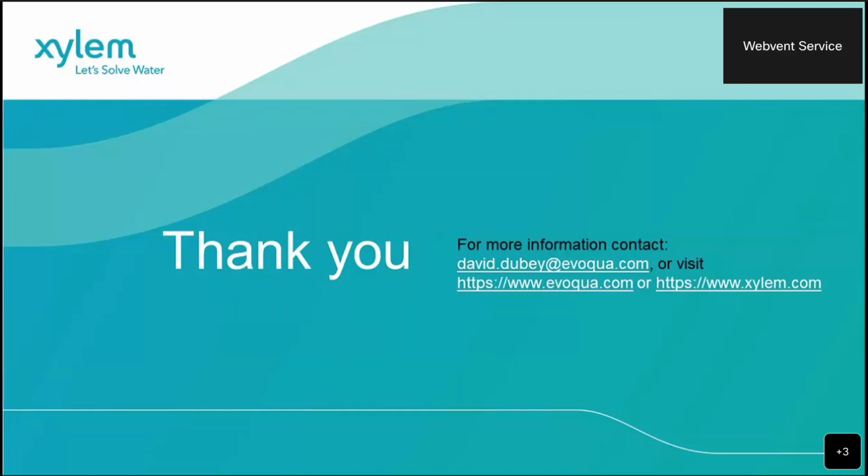And it looks like we do have time for one more question. Why is RAS 1Q? If SVI is decent, you'll get the solids back at 0.25 to 0.45Q, or is it just simplifying to make the math easier? I was just simplifying to make the math easier. Obviously, you can adjust your RAS depending on conditions at the plant. Some plants will run significantly less if they have a really good SVI, and some plants will run higher. And it also depends on how much you're trying to waste as well. That will have an effect on it.